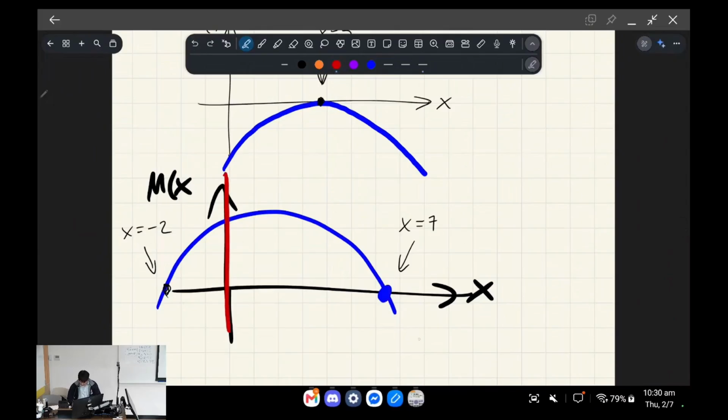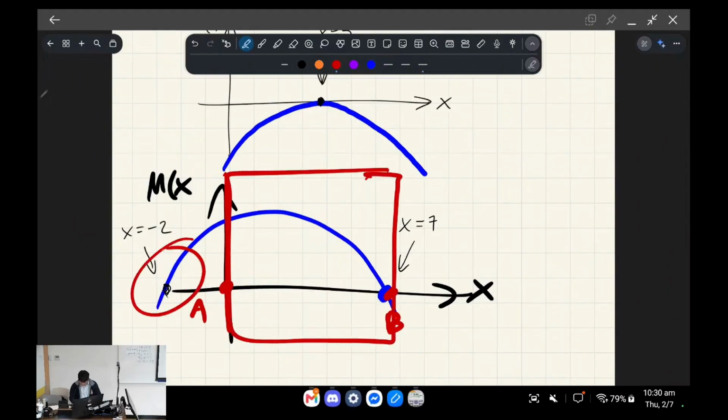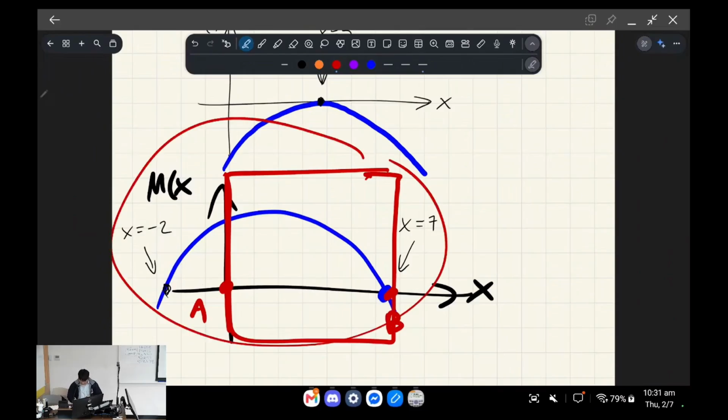So let's say this is point A on a real beam, and let's say this is point B. We'll only be graphing this region anyway. So if there's a negative root, we just kind of ignore it, if that makes sense. Even though this is like a mathematical space where you consider the negatives for an x-axis, you can think of it as parts of the parabola which are excluded. But for the purpose of graphing bending moment, we only look at the real and positive numbers.